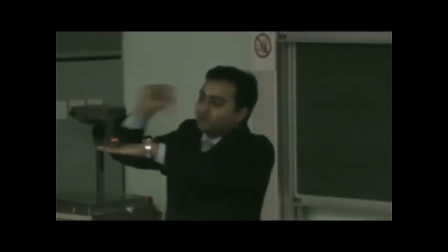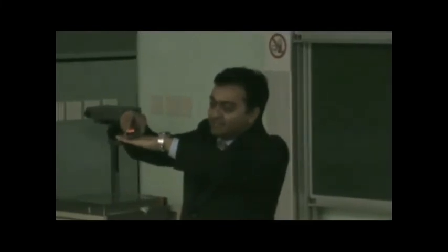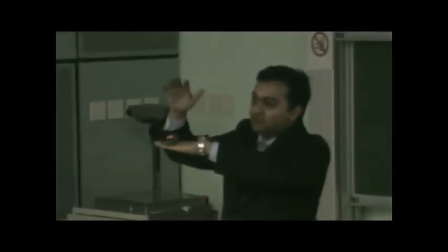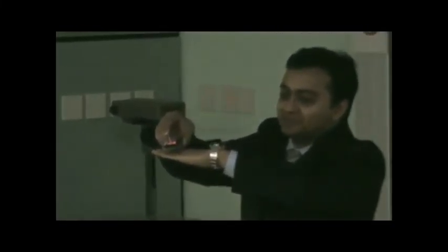The other big problem is that usually, when most of us do experiments, we have this layer and we put the contact metal right on top. Again, there is a problem. The only interaction between these two layers, according to theory, should be just van der Waals. So should there be a big difference if I put the contact here versus there?